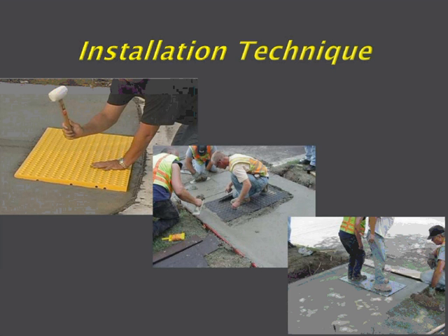The stainless steel and the cast iron products, in the installation videos I've seen, they're stepping these in like they're showing here. The one thing I'd caution is, if you're stepping them in, don't go too wild on it, or make sure that the guy on the left isn't 50 pounds heavier than the guy on the right. Because as you're on that thing, maybe rocking it back and forth, you could goof up your cross slope, and guess what? Lawyers have gone out to Home Depot and bought themselves digital levels, and they know what to look for, so they're looking for things like that.